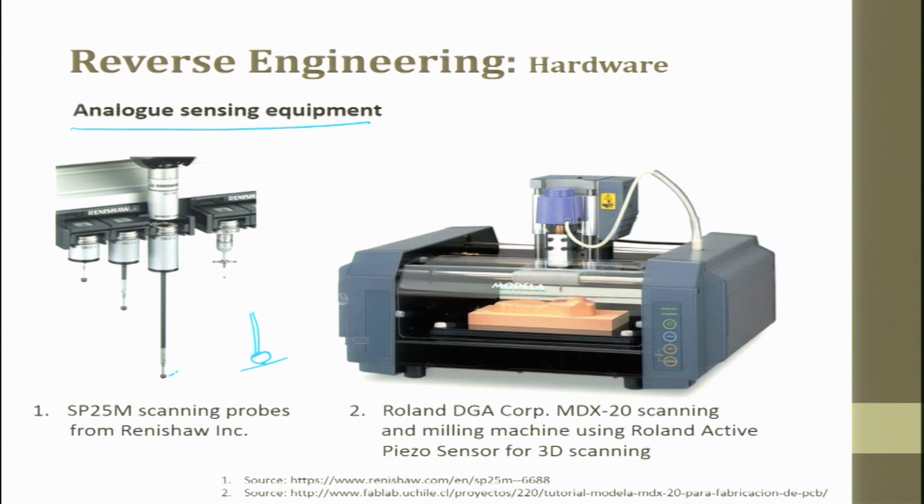So, you can see here the tip of the CMM is made out of ruby. Ruby is nothing but alumina. So, when this alumina touches a surface, this is a probe which touches, and here you will have a connector circuit breaker or a contact breaker which tries to break the circuit, and you try to get the data. So, you can see here different types: a long probe, a short slender probe, a star type probe. You can choose which one you want for your requirements, and then you can start using it.